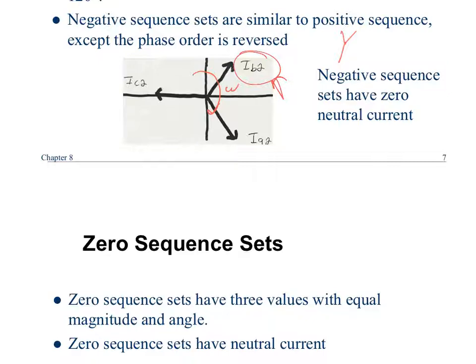So trip. One of the elements you set for certain protection, particularly for a generator, is called a 46 function. This is important for those of you who are going to work in the relay world: these are ANSI device numbers. You can look them up. There's a standard set of ANSI device numbers, because you and I know what the letters A, B and C are, and we have a common nomenclature. We know what the numbers 1, 2, and 3 are.